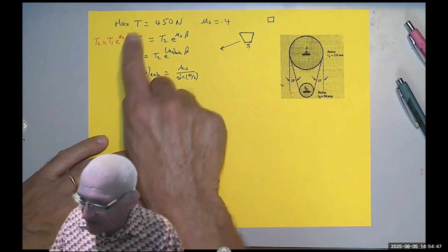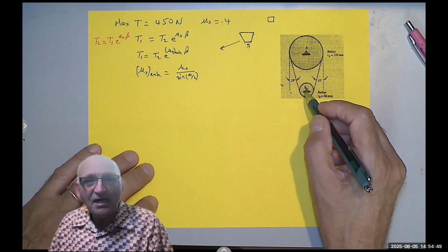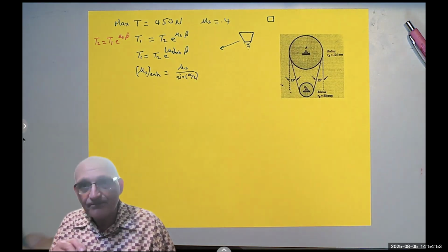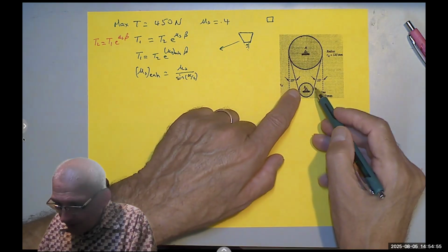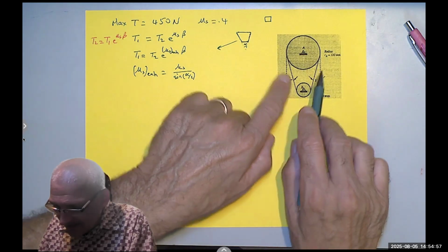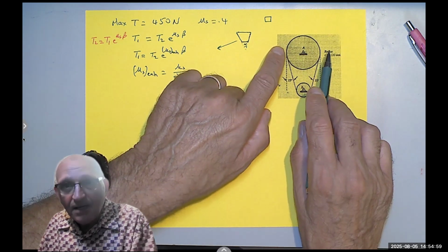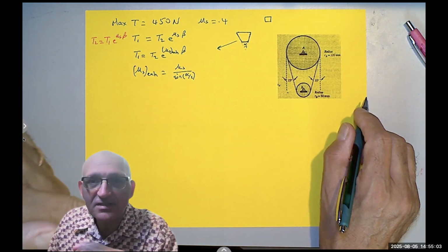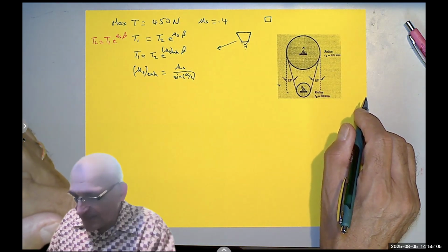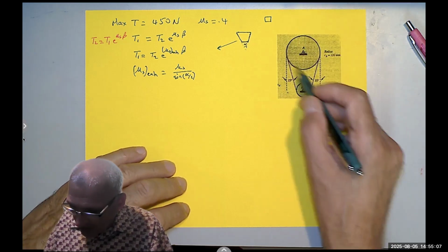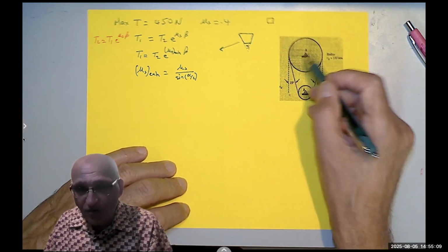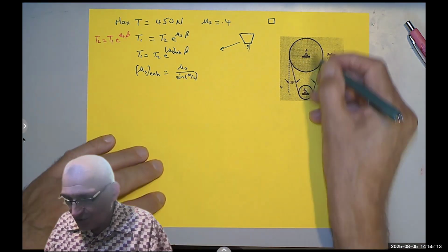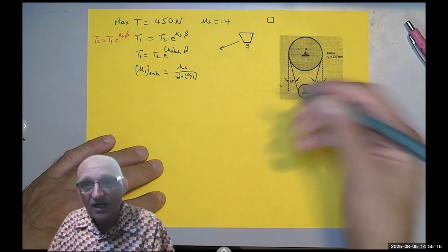Okay, so they want to see, of course, this small pulley attached to the motor rotates, but you see why the pulleys get larger and larger, because the torque equals the tension times the radius. That's why we use a larger radius for this fan or whatever you are using the motor to drive.